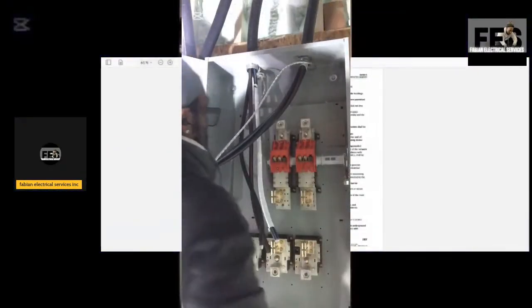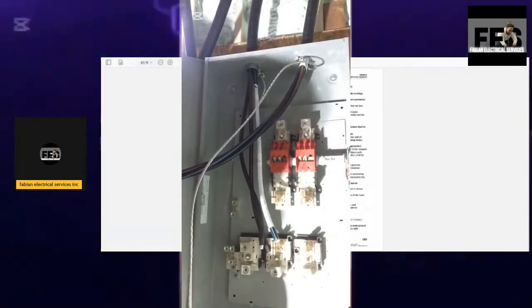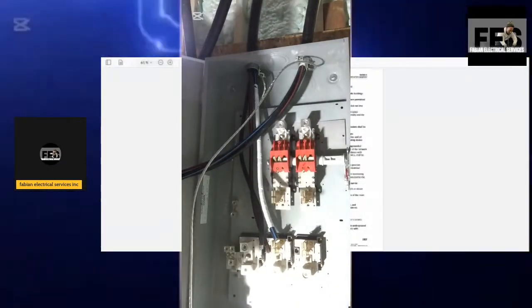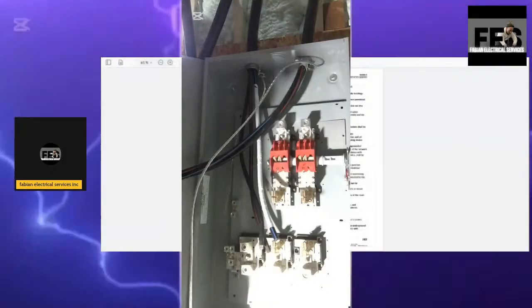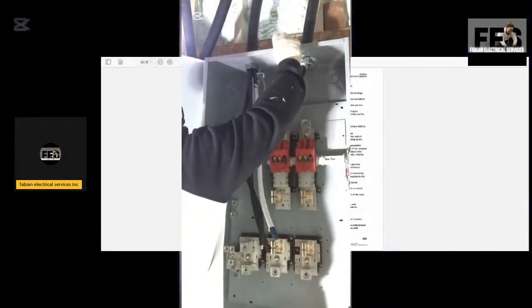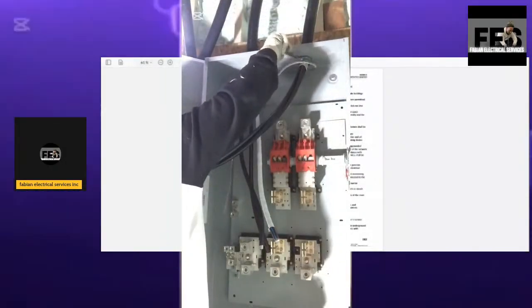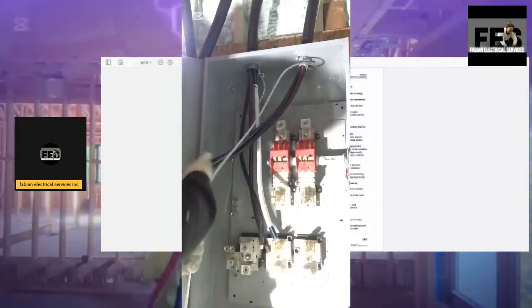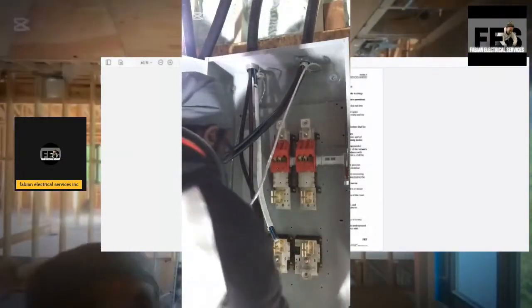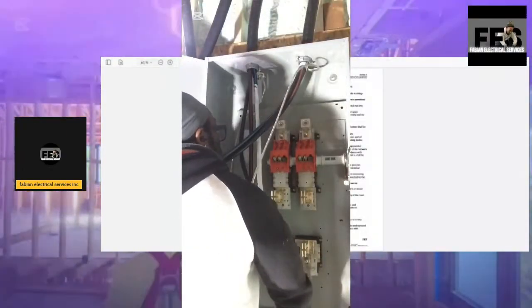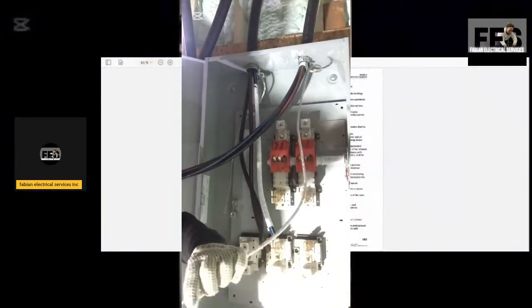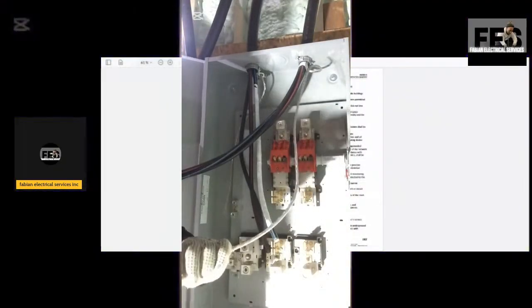As you can see, the reason I like to keep the white paper on is that it simply helps with the cable. The cable is locked in place. Once you disassemble that, it gives you a lot more problems getting the cable inside of the connector. So that's why I always land my cables inside of the disconnect, inside of the connectors, and then I remove that. Then I go ahead and ground off my ground. I do my groundings. So this is a grounding and bonding installation.